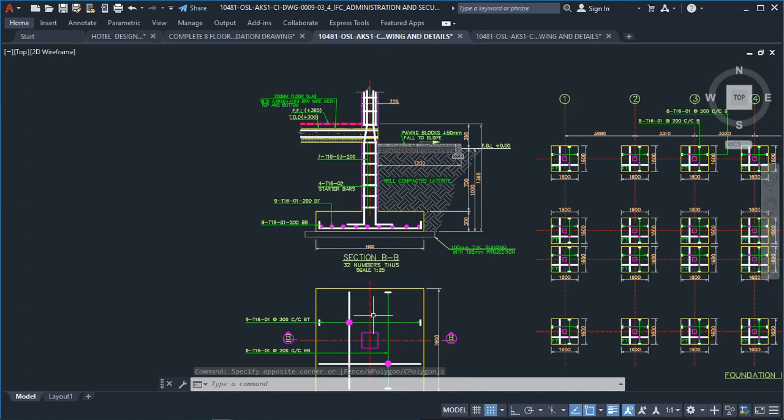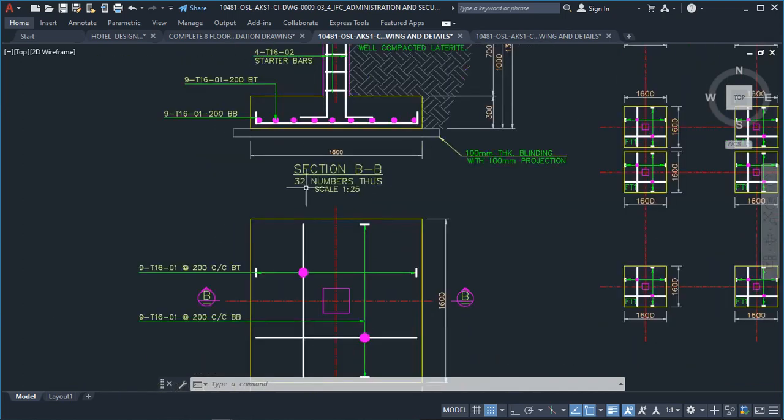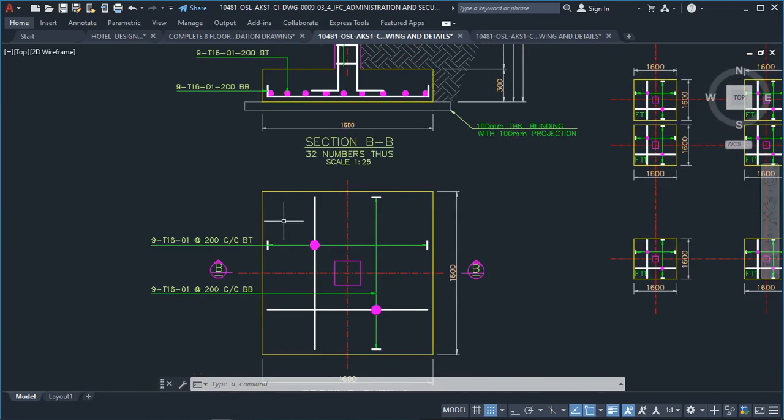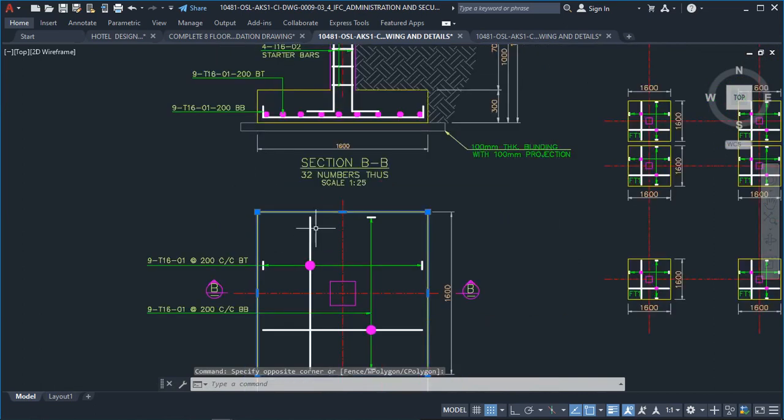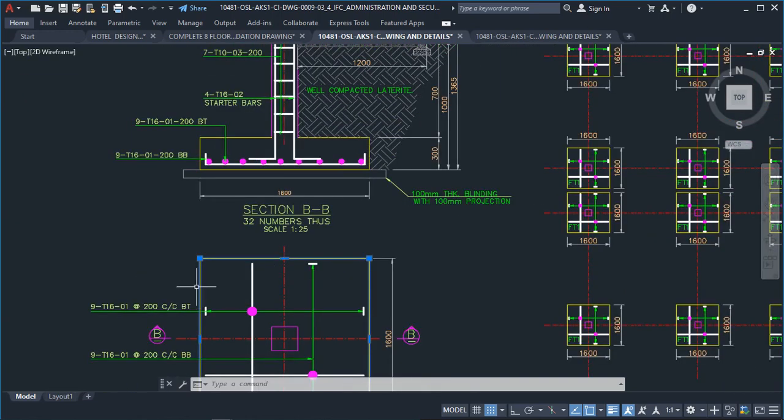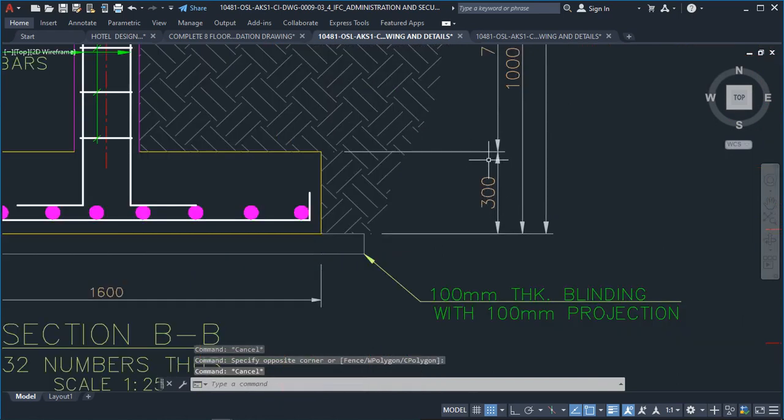So now, drawing out this elevation, the reason why you also have to go more detailed is that the person reading your drawing does not know the thickness of this footing. So you will now have to show a section of this footing. When you cut this section and elevate it, you have to visualize how it will look on site. So elevating this, you will say, okay, this footing has a thickness of 300. In my own case, it is 300 millimeter, that is the thickness.